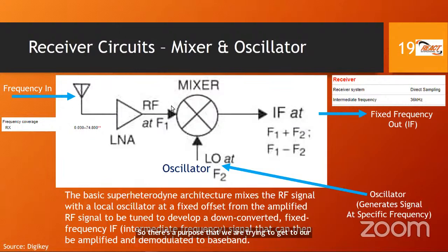So we tune our receiver in such a way that we listen to a particular frequency, but it's the oscillator that generates a matching frequency that delivers a particular output, because the mixer is taking the two and summing and differencing, and we filter out one and take the other one, and it goes to the other stages where it will detect, and all of a sudden now you are listening to a transmission. But these are the early stages of a receiver.